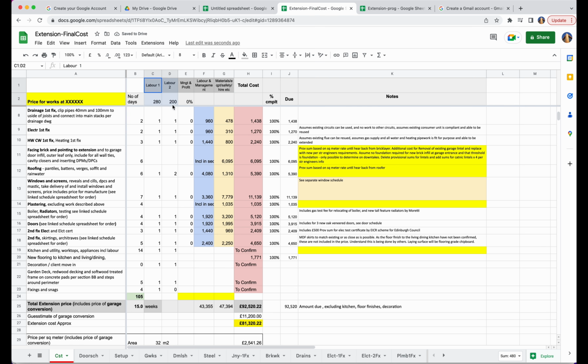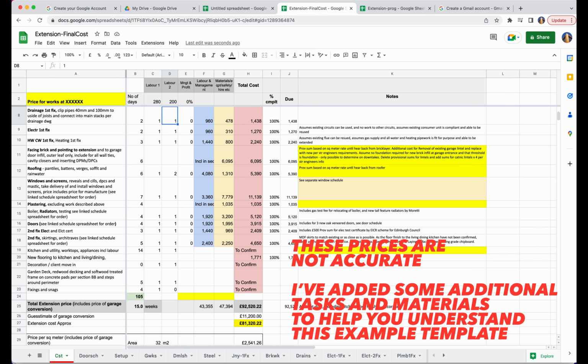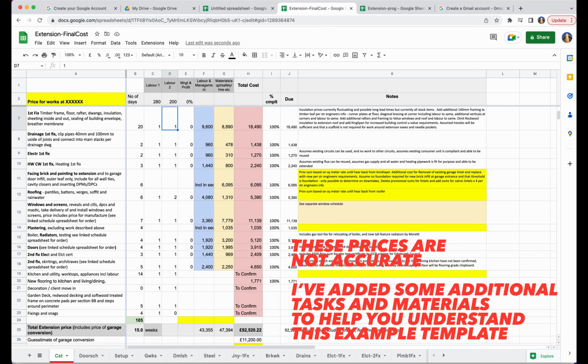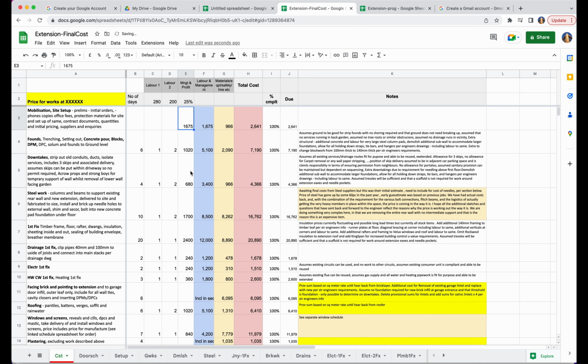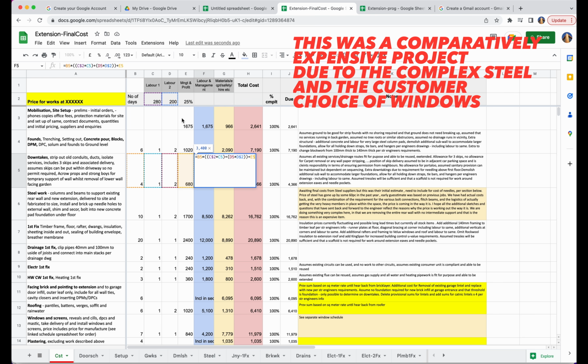I've included the rates I used for my team for the example of the house extension, but this would be a little more now given the recent bout of inflation which has affected wages. Here I've kept it simple. I've got a labourer, a skilled tradesman, and a price for a site manager or administrative person who is doing all the coordination and purchasing, which is a significant amount of time because it's essentially invisible to the people who are not used to building this themselves, and is often not taken account of when novices are considering costing of projects. I'll usually allow 25% of the labour amount, but choose what you think suits you, or just leave it out if you're doing it all yourself as a self-builder.